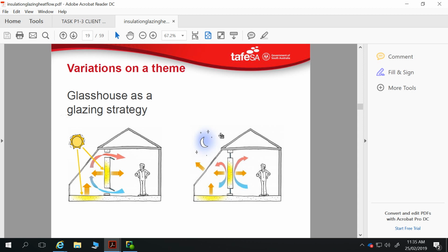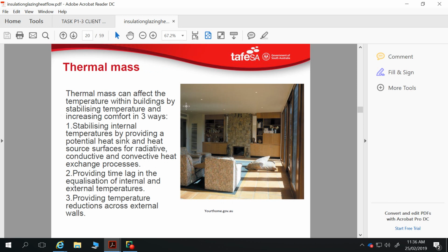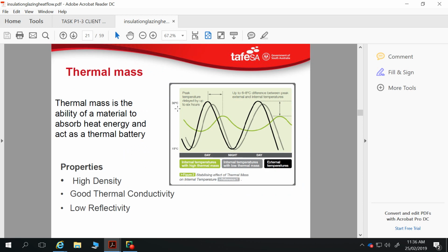And I just mentioned earthships. That's more the earthship sort of design, or if you're designing for really cool climates, in Europe for example, typically you'll have a window on a slope, because heat gain in summertime is not such a problem. In South Australia, we do have to think about heat gain in summertime. Heat for us in summer is something we want to avoid. I think we've covered that fairly well.